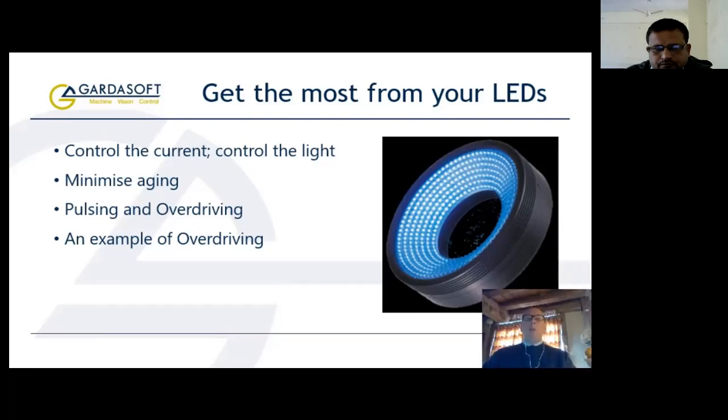SafeSense technology also ensures that the maximum current rating for the LED is not exceeded during continuous operation. The heat generated within the controller itself must also be controlled, and Gardasoft designed its Safe Power technology to minimize the heat dissipation in the controller by automatically adjusting the lighting supply voltage. This allows lighting to be driven with high continuous currents without heat sinking the controller.